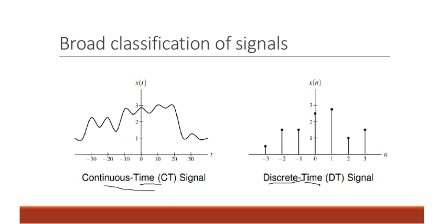So these discrete instants of time are labeled as the 0th instant, instant 1, instant 2, instant 3. It depends on what the units of your time instants are. Maybe it is after every 1 second, after every 2 seconds. It depends on the measurement. So here the measurement is not done for all instants of time, and hence it is called a discrete time signal.